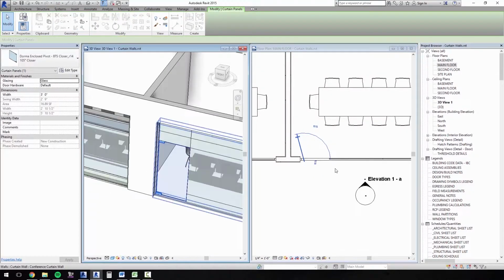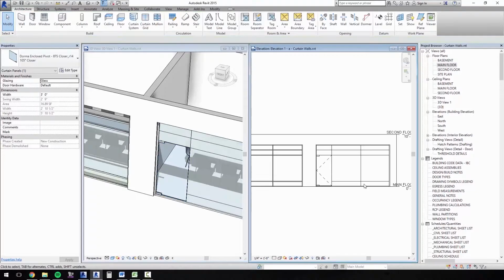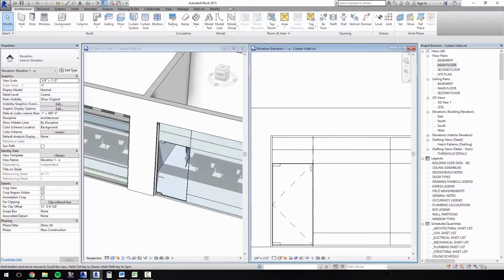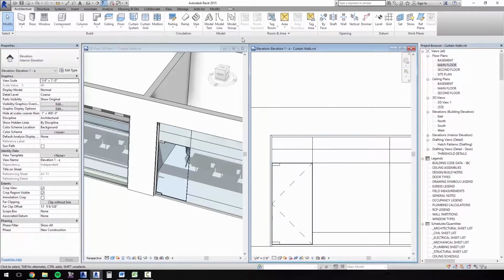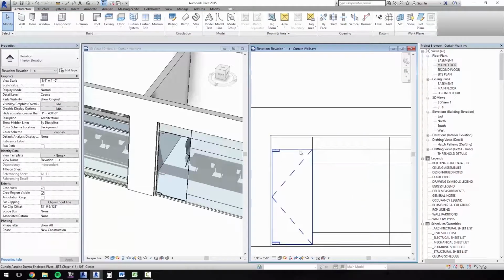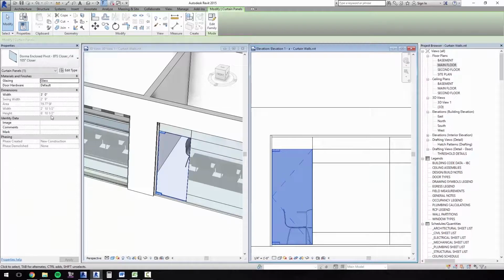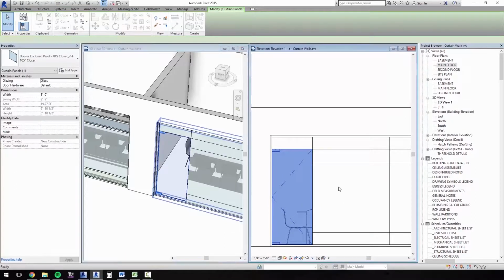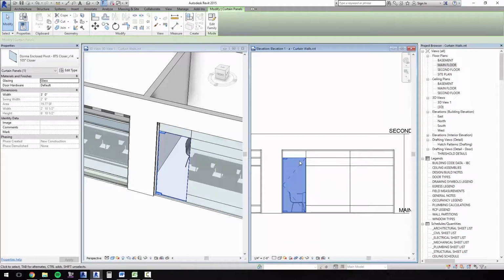Okay, I also just noticed we have the wrong height for that as well. So what I'm going to do is remove this panel. Again, I'll select the grid, I'll remove segments, and now you'll see the door fills in the exact panel that I want to get it to the correct height, 610.5. Also note that the panels will shrink or grow depending on if the mullions are in there. So I'm going to come back to that door in a second.